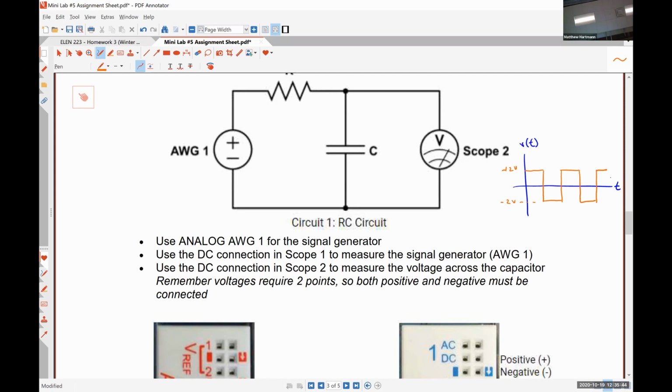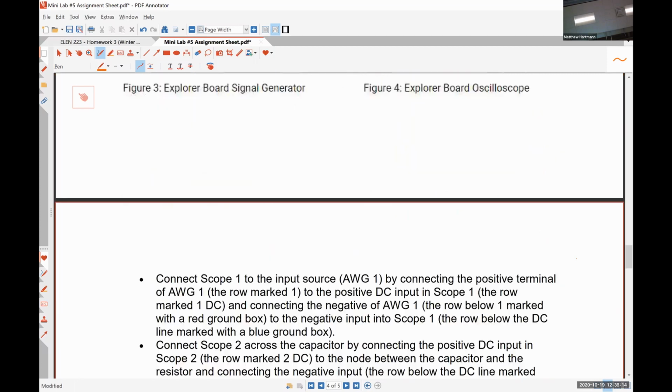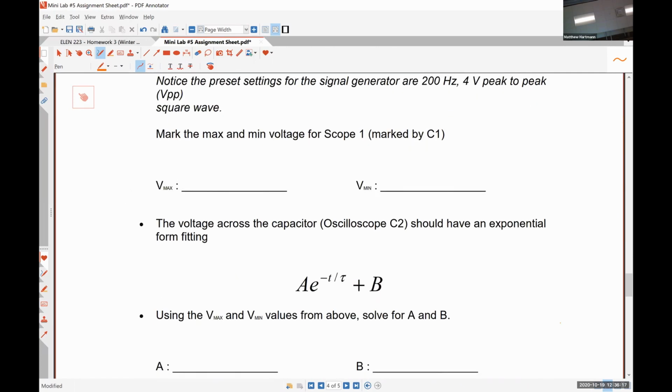I will look at a graph in a moment, but effectively if we have the frequency right on our square wave, such that the duration of each interval is long enough for our signal to decay, every time we change state, we can treat that as a new t equals 0. It just depends on if we want to look at a charging cycle or a discharging cycle for our capacitor, which is what we'll talk about in just a moment. So we've done all of this kind of stuff. Now we need to actually look at our waveform.